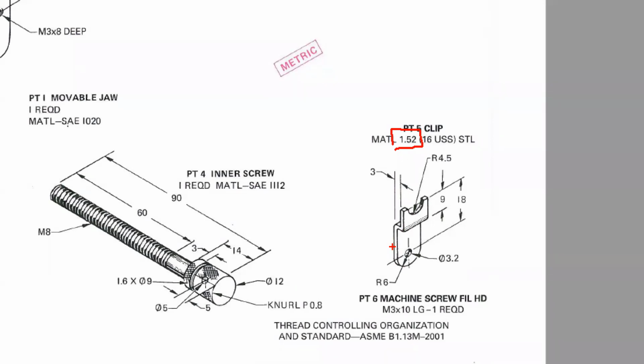The only thing I normally see is when you bend these sheet metal pieces. I don't know how good I can sketch it here, but if you're not careful, these bends get messed up. Whatever radius you use, use a real small radius here. It doesn't tell us what the bend radius is. This would be based on what kind of tooling you have in your shop to make this part. But say this radius is 1 millimeter. Just use something kind of small. This outside radius here would be that 1 mil.